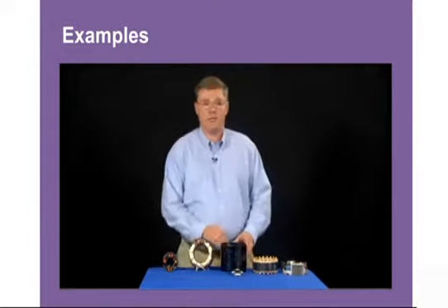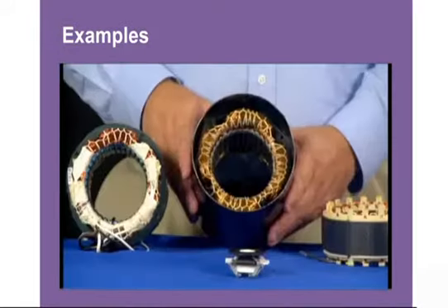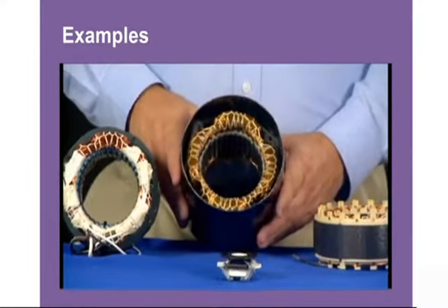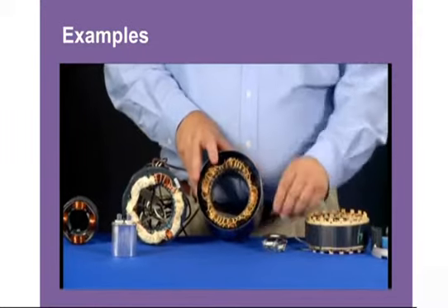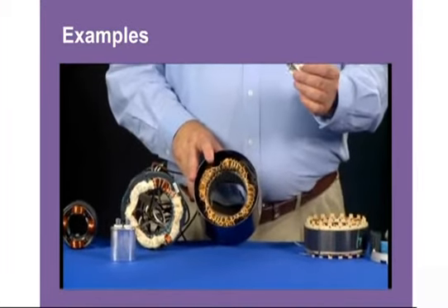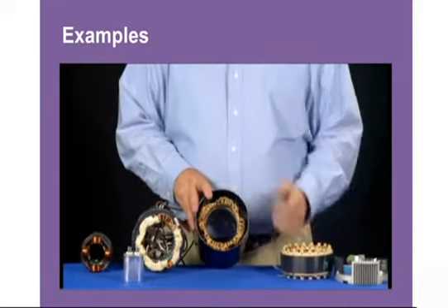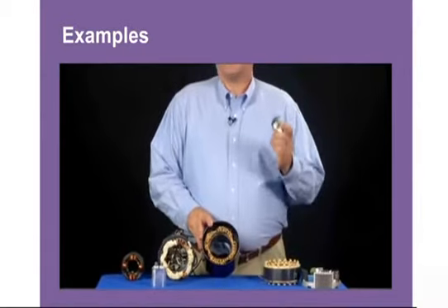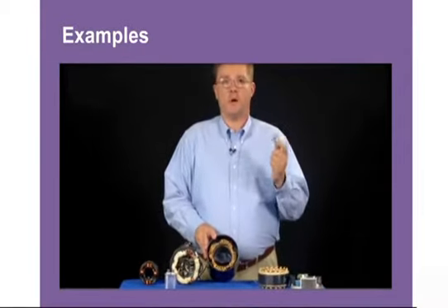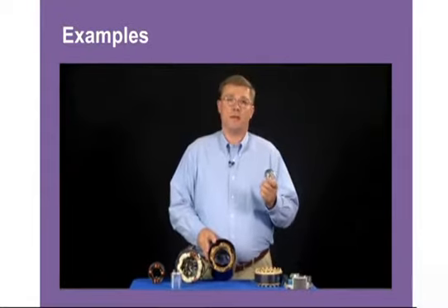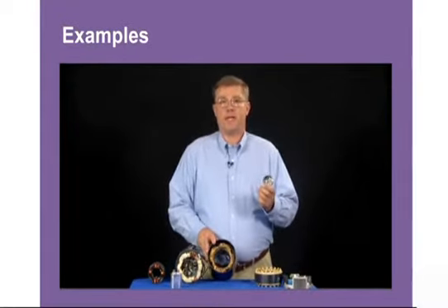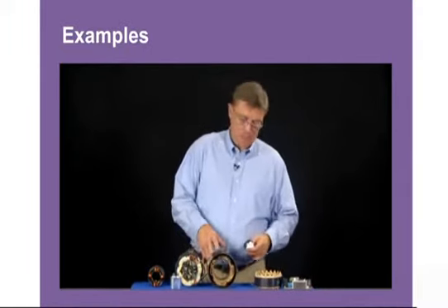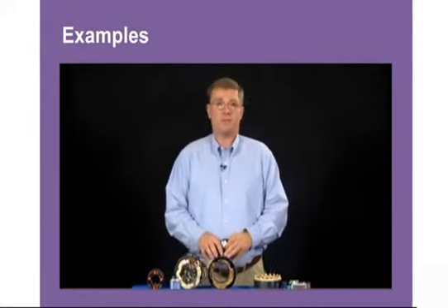The next type of motor we talk about are split phase motors. This type of motor also has 2 windings in it, an auxiliary start winding and a run winding. But what makes split phase motors unique is a centrifugal switch. This switch allows the motor to start on the auxiliary winding, which you'll note is a very fine gauge wire. It's designed to slowly come up to speed, and since centrifugal force opens the switch, it allows it to go to the run winding. This motor's typical belt drive application allows it not to take off immediately and throw the belt off the line. There are three types of split phase motors.